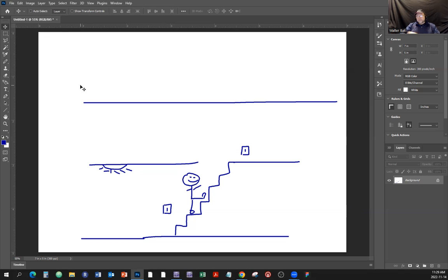So that's the idea of the whole thing. Now, there's also a possibility of using more than two switches. You can have one here in the basement, and you can have one further on the other side. But in this case, you're going to have to employ a four-way switch.